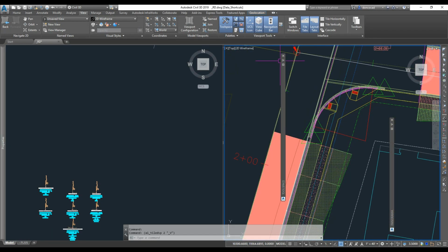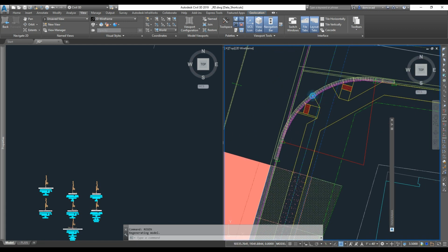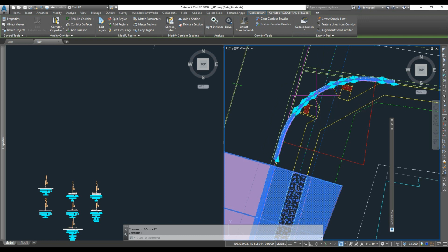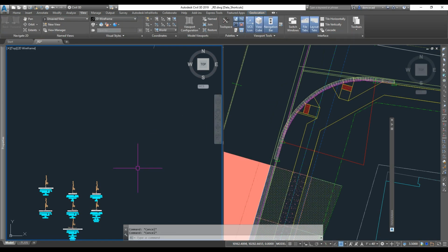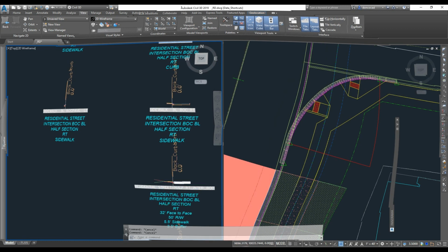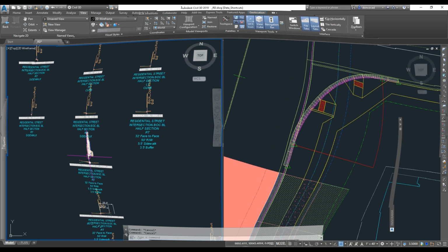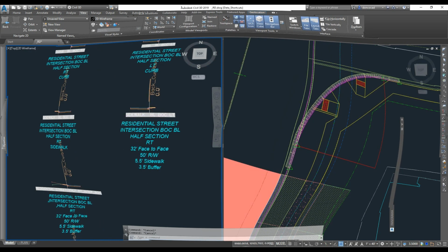Okay, so I brought that detail in from the city standard on the intersection for the ADA ramps, and began modeling. And what I did is create feature lines on my face of walk there, and I also started a curb corridor, but I made a feature line also for the back of walk line I would later use for the baseline to model that sidewalk through the turn over. Got a lot of assemblies in, man, for all kinds of situations.